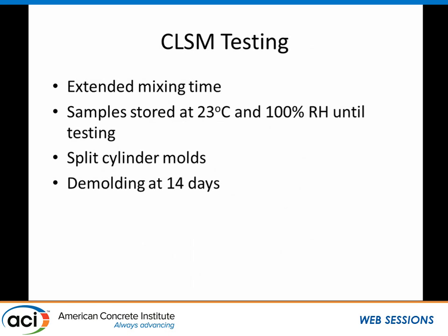The CLSM testing, we had this extended mixing time, so we wanted to make sure that what we were doing in the laboratory would account for the fact that these materials have to be very friendly in the field. The samples that were cast were stored at normal curing conditions, room lab temperatures and 100% humidity until testing. The 100% humidity was important for the subsidence measurement so that we're not getting a drying shrinkage problem.